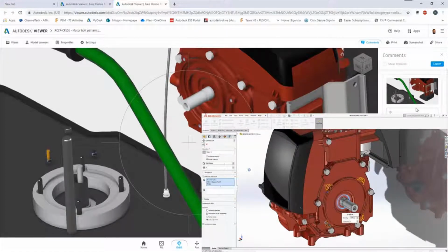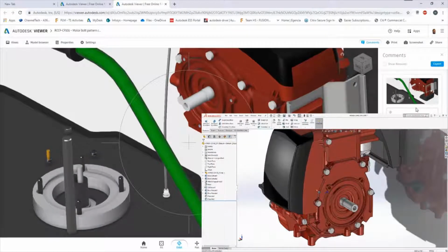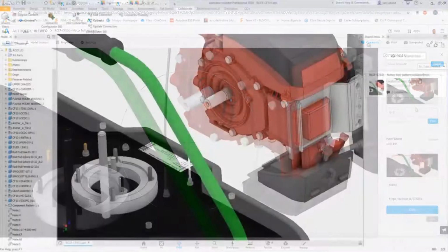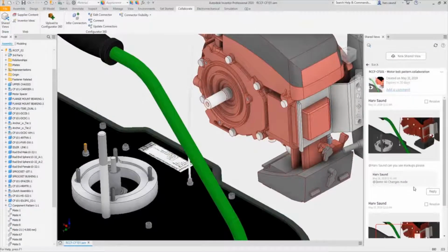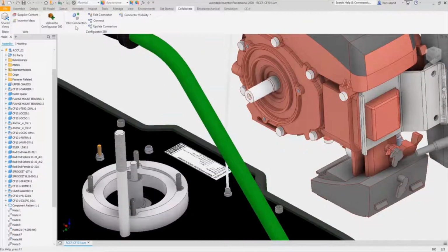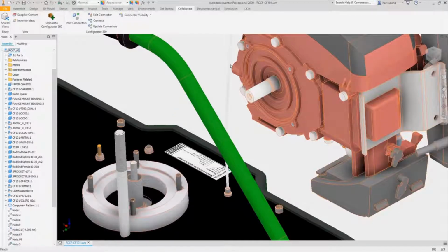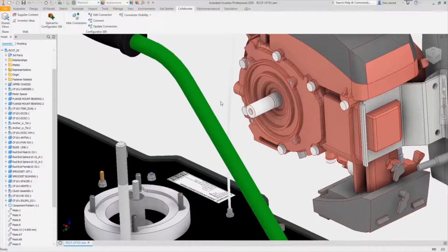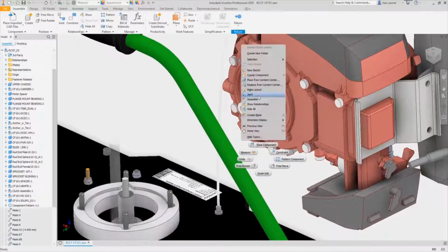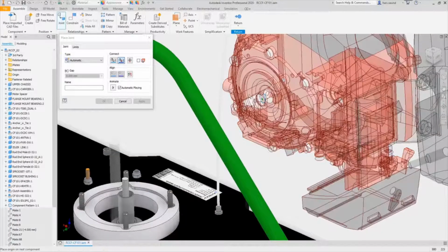Eventually, they'll get the design to 4 holes, and they'll let us know that they've made their changes by sending us an update through the design view. We just do an update to our Inventor model. Those changes come through as if it was a native Inventor component. From here, we can do our final assembly and do all of our design checks as normal.